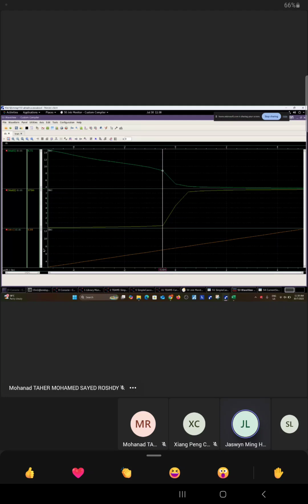But I don't really think we should worry about saturation. If you can work along this region, it's saturation already, because at saturation your V out increases linearly with V in. Yeah, that's the region you're looking at. Just that the first stage doesn't seem that nice, but the second stage is quite nice already. I think this is what matters the most. And the good thing is your first stage doesn't hit the maximum that quickly. I think it's quite nice actually. Good improvement already.